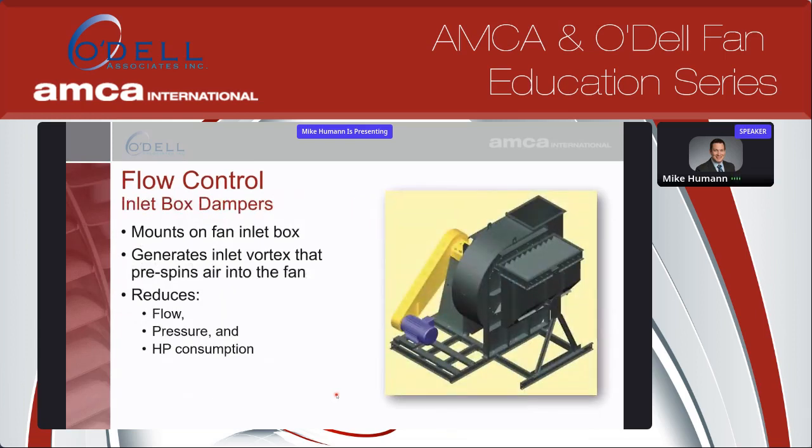And the last type is you can mount what comes out to be a parallel blade damper on an inlet box. You'll see here on the right-hand side, you have the inlet box damper mounted on top of the inlet box. And it does the same effect. It pre-spins the air into the fan, detuning the fan.